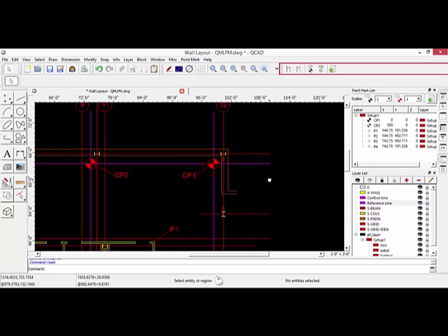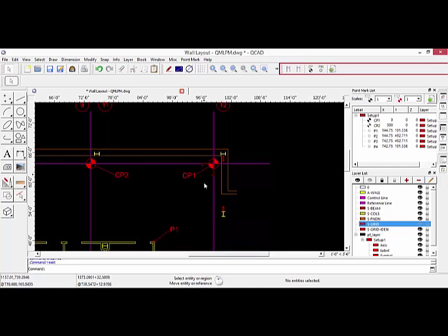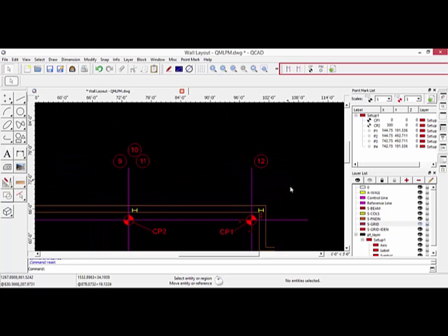If I don't know the actual layer of that, like I said, you can go ahead and click on it, and you'll see that on the bottom here it says select entities, and it gives you what the layer name is. So for that layer right there, I'm going to click on the little eye icon, and I will turn off the actual grid lines.